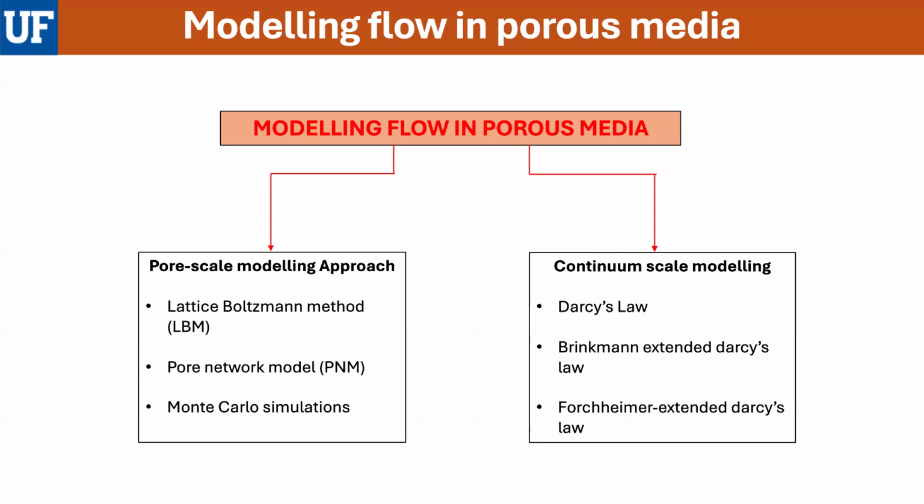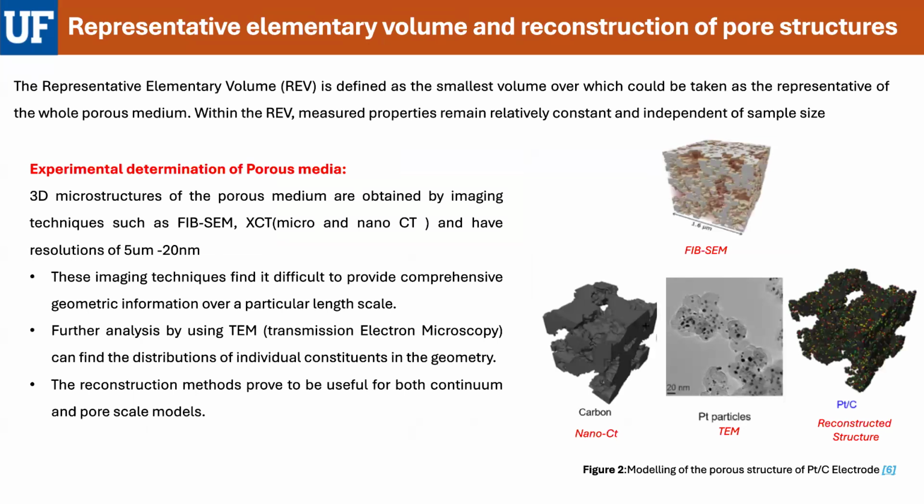So what is this representative elementary volume? The representative elementary volume is taken as the bridge between the continuum scale and the pore-scale model, and it is used to define parameters such as permeability and porosity of the porous media. It is defined as the smallest volume which effectively represents the whole porous media. One main condition imposed in the REV is that the measured properties, such as the permeability and porosity of the porous media, generally remain relatively constant along the REV.